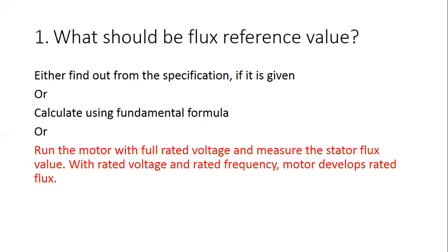So I simulated the motor with full direct online rated voltage, and then when it was in steady state, I measured the stator flux. And that is going to be the rated flux, because with rated voltage and rated frequency, the motor is supposed to produce rated flux, right? So that's the concept, that was the way I did it.